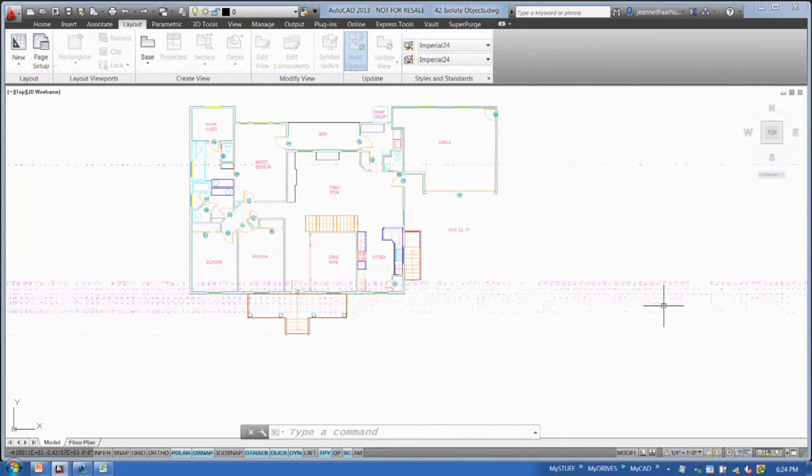What grip lets you add a vertex on a polyline? Not the square. Dash. That's what I was looking for. I think it's a dash. Don't you think it's a dash? The square ones are on the corner. It's the dash ones that are at the midpoint.